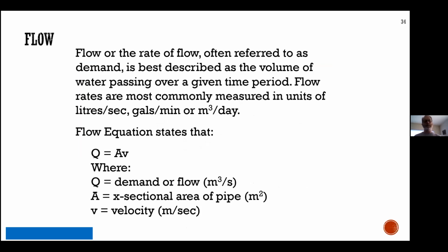So we talked in the math, just moving on to the next concept of hydraulics. So we've moved from static head to dynamic head. And of course, as water moves through the pipeline, now we can start calculating the flow. And we did this last week, right? Q equals A times V. So flow, typically in cubic meters per second, is a product of area, the cross-sectional area of the pipe in square meters, and the speed, the velocity that is flowing in, right? So that's how we get cubic meters per second. So we end up having a volume, cubic meters, over time, seconds.